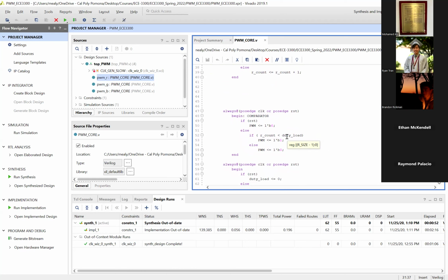What is this, literally, in the PWM? Do you remember the positive edge and the negative edge? Do you remember the clock? In the clock you already have high, low, high, low, right? So the size of the high is equivalent to the size of the low. The clock is just like a pulse. When you go high, the duration of that part is equivalent to the low. But in PWM, no. The part of the high, we call it duty cycle, which is the active part of the clock.